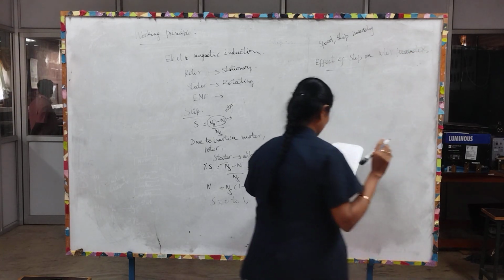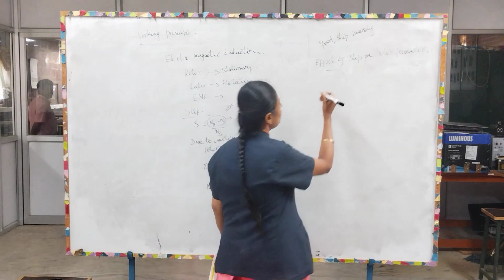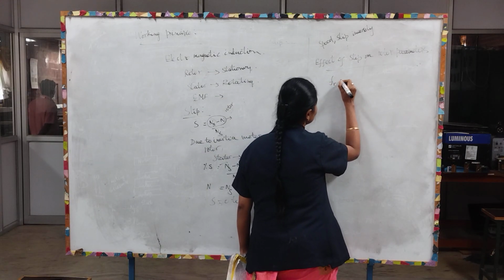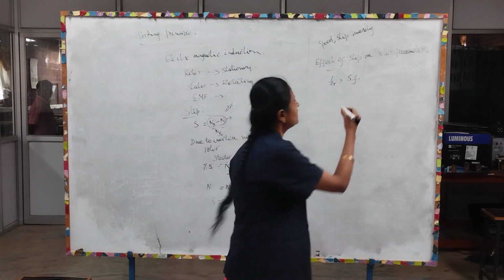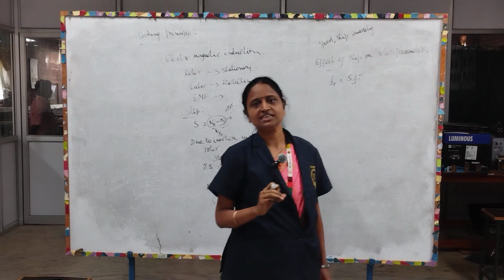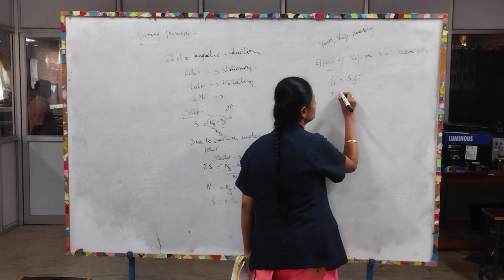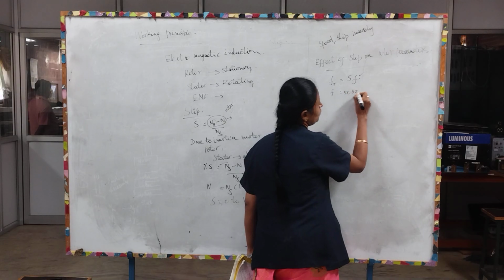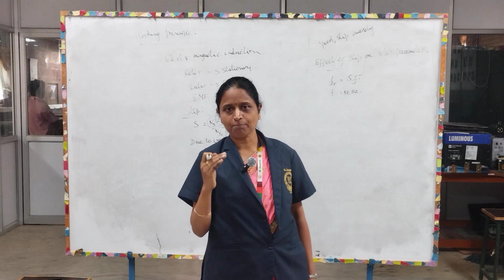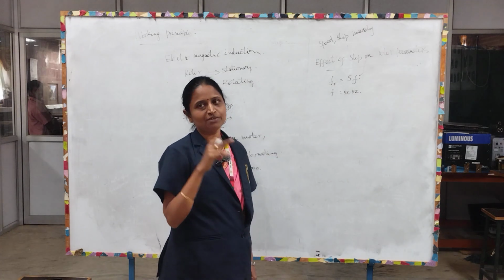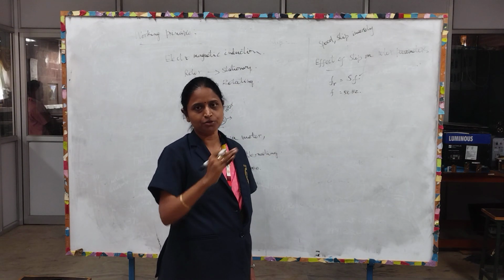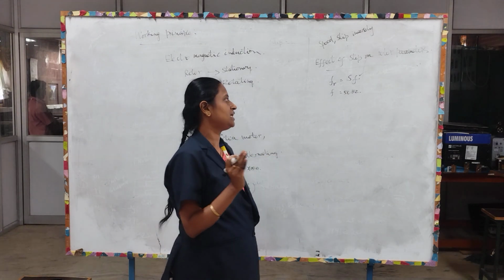We have to discuss the frequency of the rotor, that is slip times the supply frequency, where f is the supply frequency, 50 hertz. When we give a three-phase supply to the stator of the induction motor, a rotating magnetic field of constant magnitude is produced and its axis continuously changes.